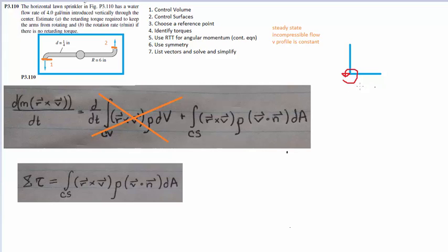And if you remember, your force vectors are sliding vectors, so that means you could move them along their line of action and preserve the system. But your torques are free vectors, which means I can move this rotation wherever I want, and it's going to preserve the system. For that reason, I'm going to drop the vector notation when we're discussing torques.